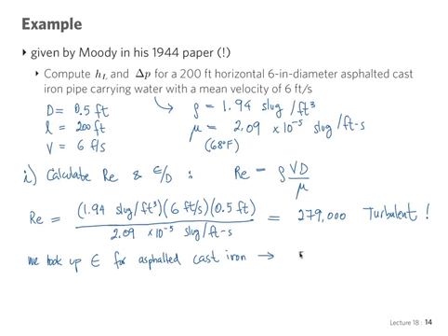And get epsilon equals 0.0004 feet. And so we get the relative roughness, epsilon over d, is 0.0004 divided by 0.5, and I get 0.0008. This is, of course, without units, it's non-dimensional.